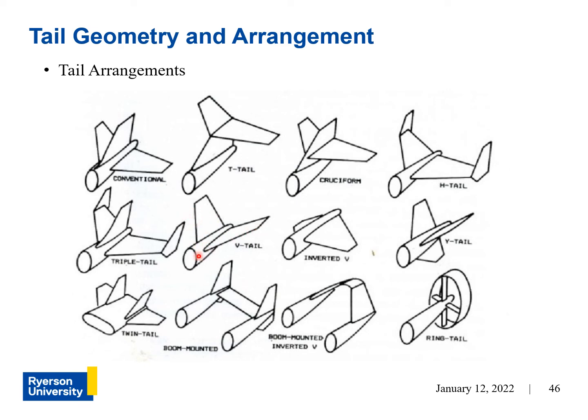So the aerodynamics of a V-tail is a little bit more complicated because for a conventional tail, you can easily separate the function of pitch stability and yaw stability, whereas for these two, they're basically integrated. So one is affecting the other more directly because they share the same surface for two different stability purposes, if that makes sense.